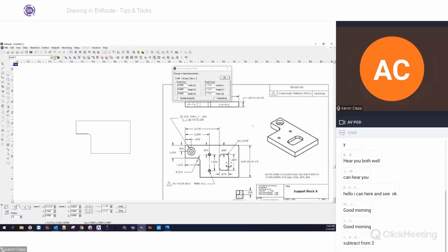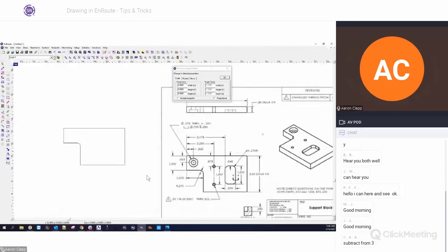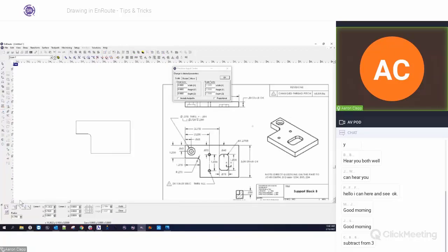So I can go 0.270, and I could create a rectangle with the radiuses already placed on. Now, the reason why I'm not going to do that is because I need the alignment to be set straight. So we need to find out where to put this, and I'm going to use the sharp corners of my rectangle in order to get the positioning right.